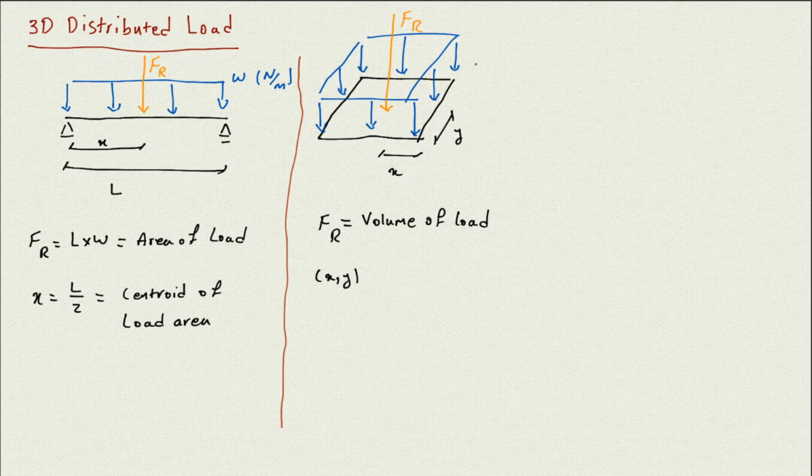Similar to here, you have the load creating a volume, and that resultant force would be at the centroid of that volume. So you find the centroid of that load volume, and wherever that centroid is, that is where the resultant force would be active.